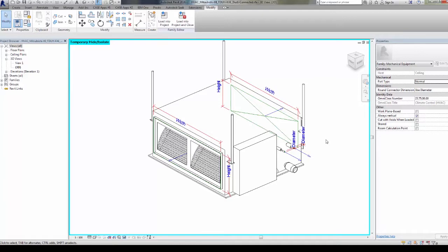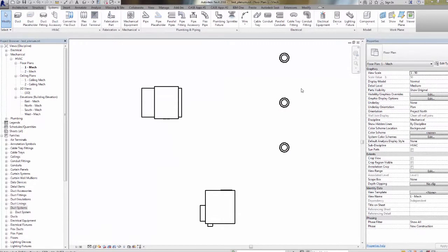We are now starting by placing the plenum. Considering already introduced the air supply outlets, each of them for its corresponding zone, an indoor unit that will be the mechanical HVAC system, we are also considering that there is a fresh air unit plus here. First thing we need to do is to insert our plenum.